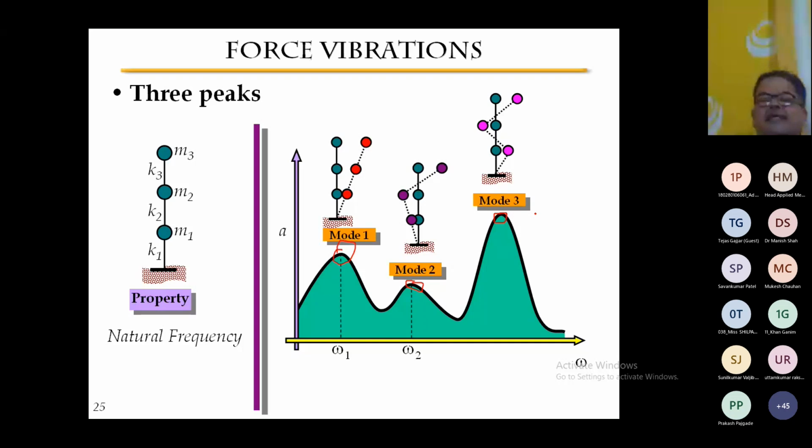Now the question will arise, in which mode is your system going to respond more, right? So it depends. For example, if my structure has 3 frequencies, for example 3 hertz, 10 hertz, and 20 hertz, right? Now if the earthquake which comes contains the 10 hertz frequency, then the response in the second mode will be higher.